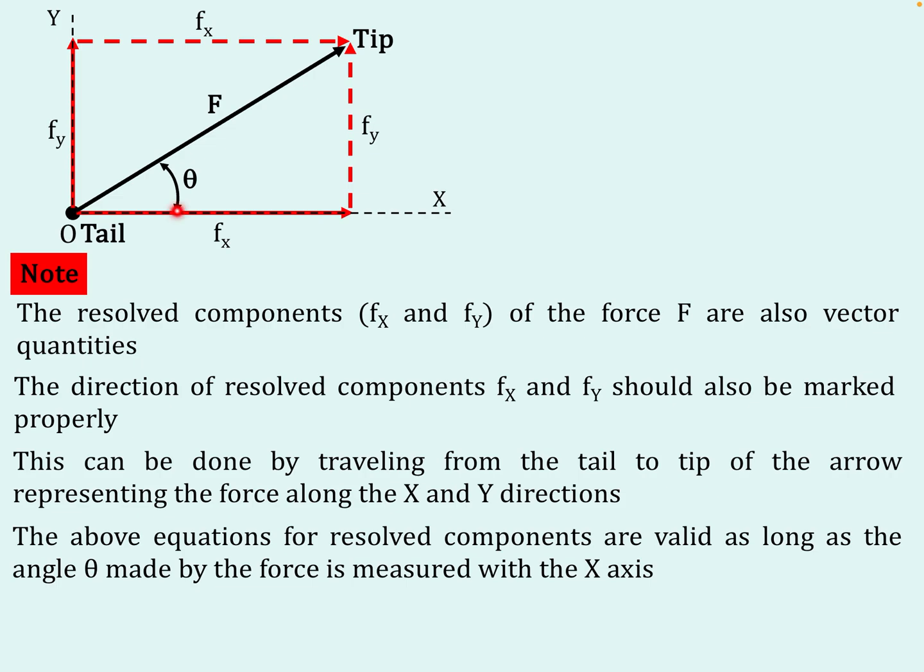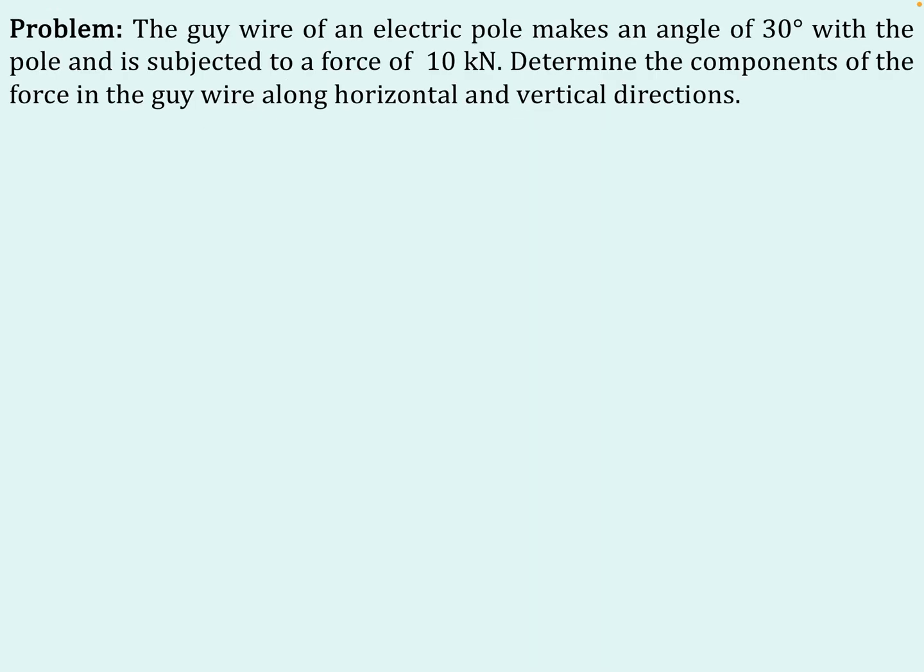But please note that the equations for Fx and Fy are given as what? Fx is equal to F cos theta and Fy is equal to F sin theta, provided the angle theta is measured with respect to the x direction only. But if the angle made by the force with the y direction is given, these equations won't hold good. We always have to consider the angle made by the force with the x direction, so that the x component is F cos theta and Fy is F sin theta. So with this knowledge, let us try to solve a numerical problem.